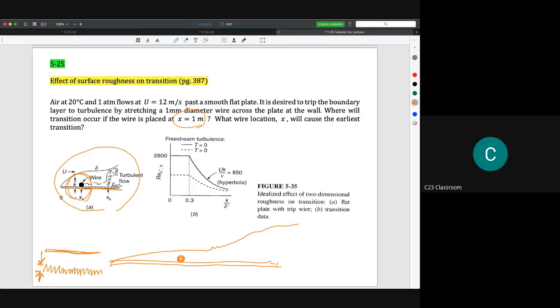I think it is an advantage for you to see the basic idea of roughness measurement, because normally we will have Ra and sometimes Rv or Rp and so on. It is actually to reflect the height of the peaks and also the valleys of the topography for a certain surface. So this is the idea.